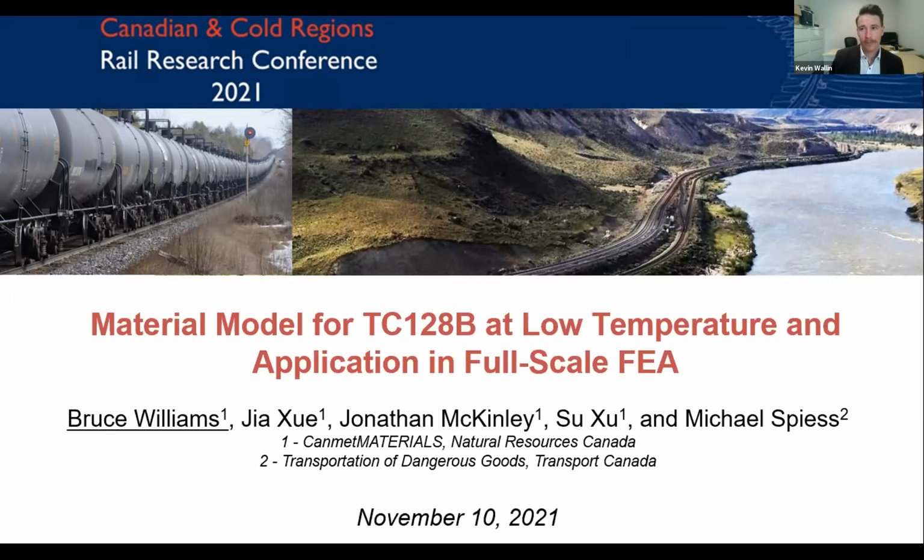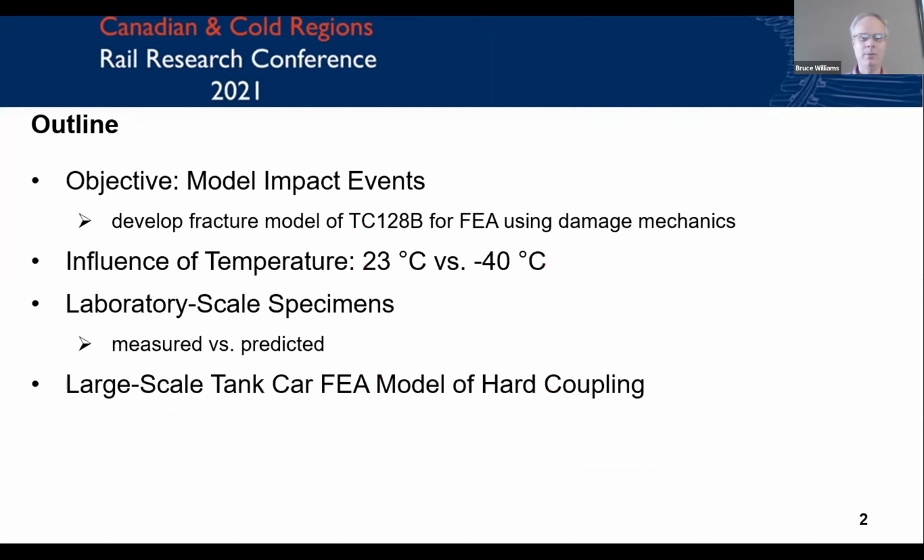Welcome, Bruce. Thank you. So today I would just like to talk about our material model for TC128B. We saw a presentation yesterday on this, and this expands on that. We'll be particularly talking about the low temperature material model and its application in full-scale finite element analysis. And why do we want to use full-scale finite element analysis? That's to model impact events. It's very expensive to do this experimentally, and particularly at low temperature.